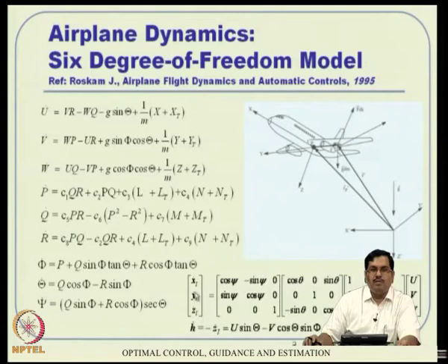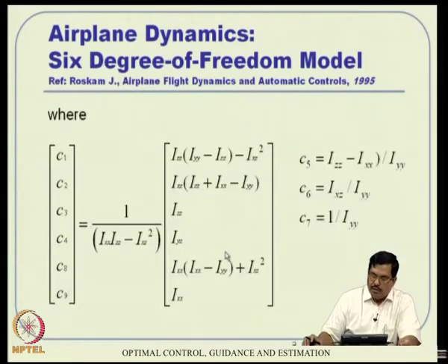So, psi and xy you can probably decouple that and say, okay, even if there are actually 12 equations, under the non-rotating flat earth assumption, I can just work with 9 equations as far as local control design is concerned. Control design is typically local, it is a short duration stability problem, not long duration effects. So, that is fairly okay.